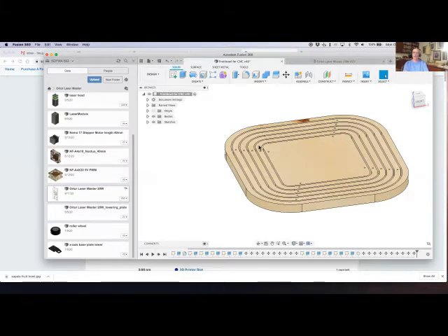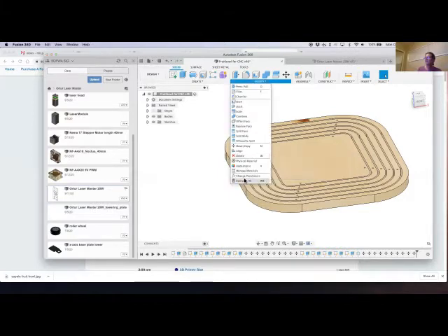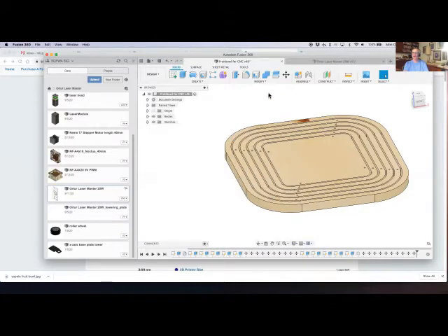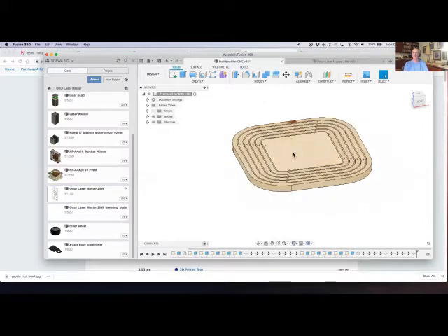Is that 1/8 inch? I used 1/8 inch in this case. Okay, and the software you're working with allows you to create an 1/8 inch rectangle all the way around, and then it goes multiple times for different depths, and it just makes one cut all the way around.